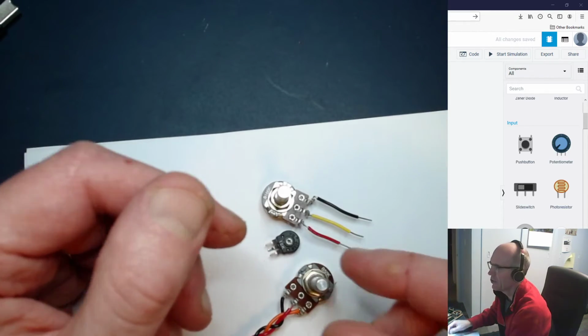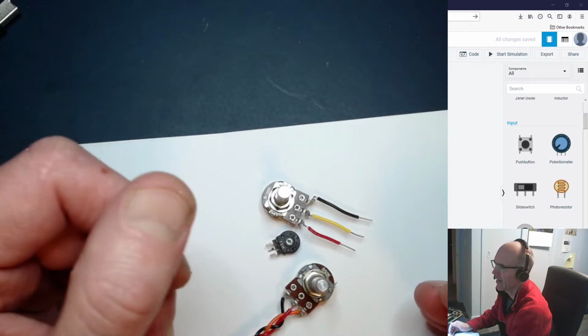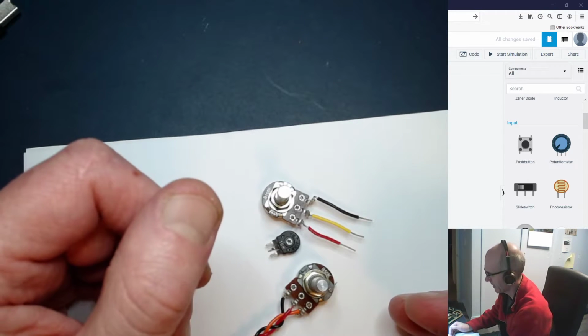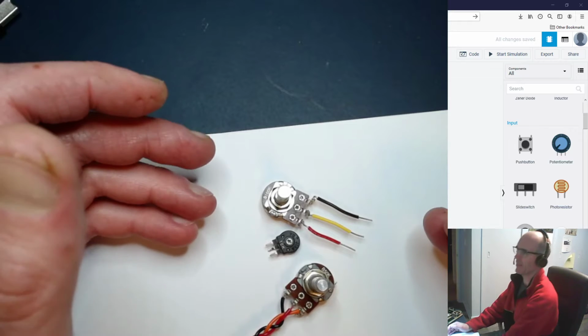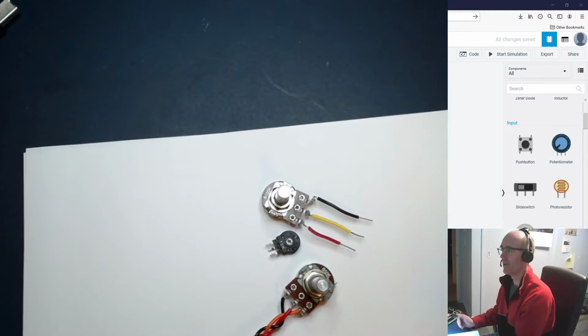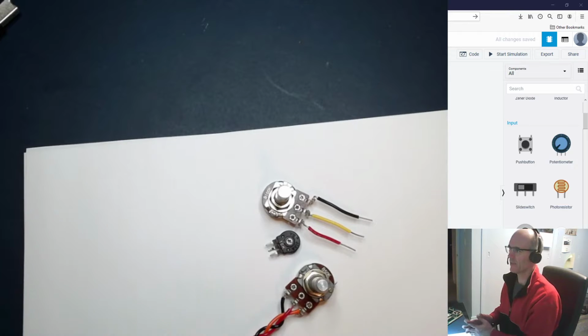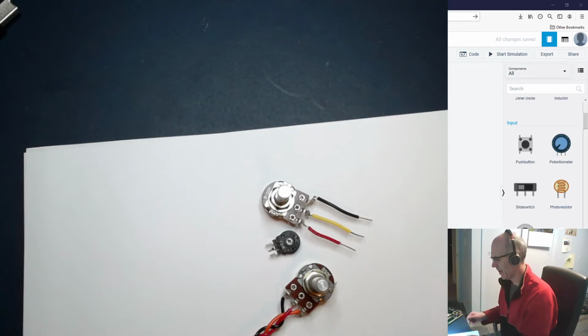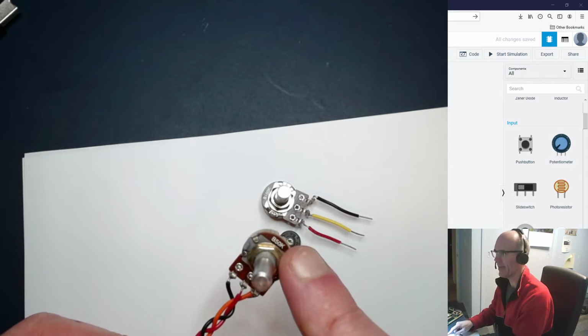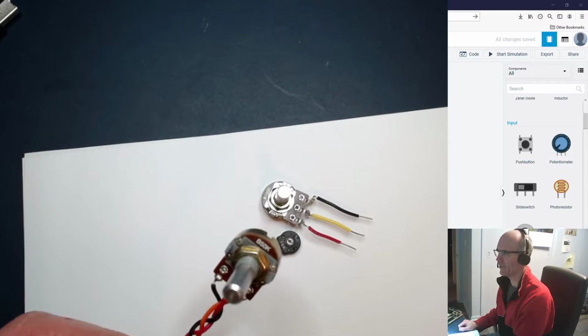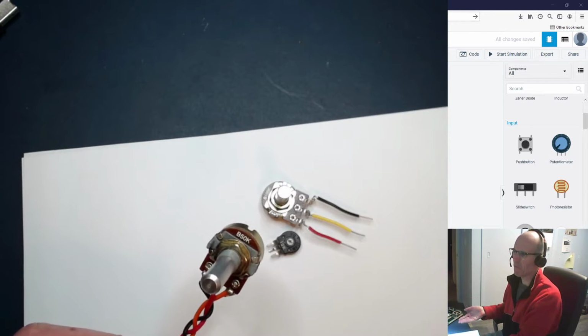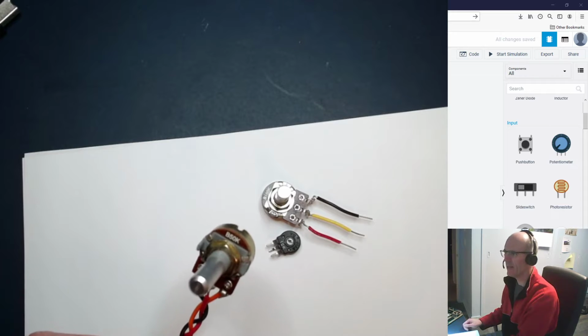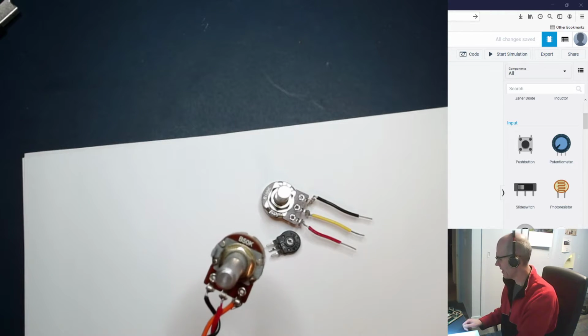That's in comparison to an audio taper or logarithmic taper potentiometer that are used in specific applications, as you might guess by the name, audio. Because in audio, if you're going to increase the apparent sound volume of something, you can't do it on a linear basis because our ears don't pick the sound up that way and the energy doesn't travel that way. So if you see one that says A 50K, then you're dealing with an audio taper, and it'll work, but maybe not so well. We're looking for ones that say B on them.